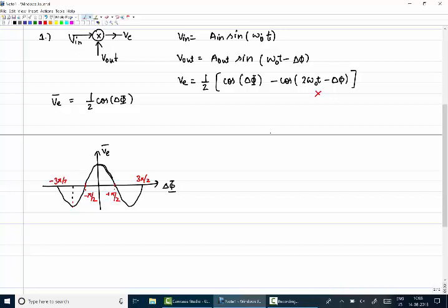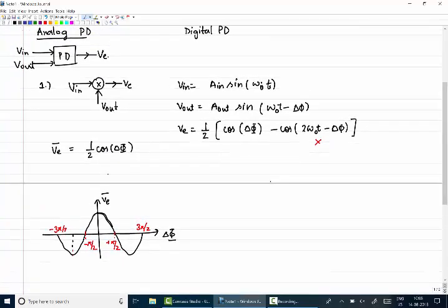Now you see that the output of this phase error detector, first thing, is non-monotonic for a given input phase error. It is non-linear also. So if I want to use this in a PLL, in any feedback loop, if I want to approximate this as always a negative feedback, which section of this phase error detector would be useful for you?